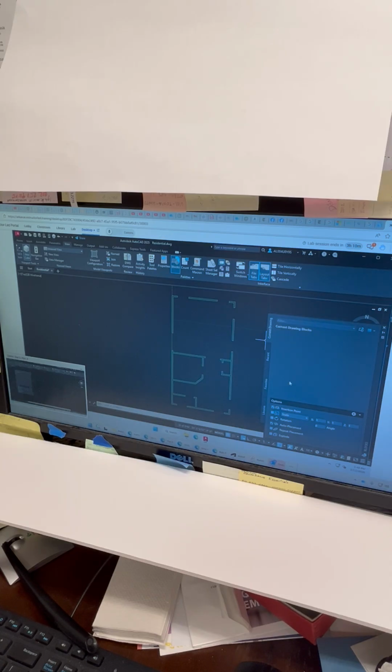All right, here's the other thing also. When we get this window to come into this drawing, it's going to be attached to our cursor at what we call the insertion point. With a drawing being used as a block, the insertion point is the origin of the drawing, and the origin of the drawing was 0, 0. So you're going to see how that window is attached at that insertion point.